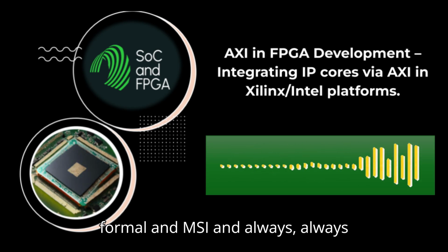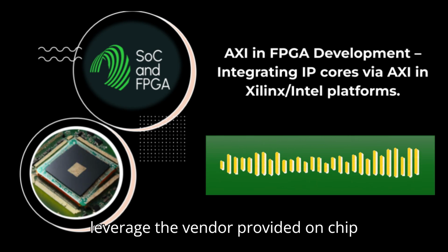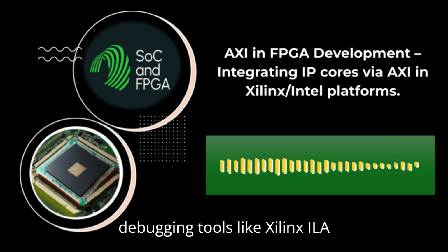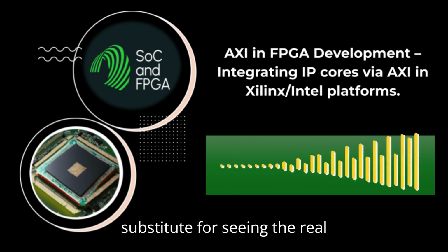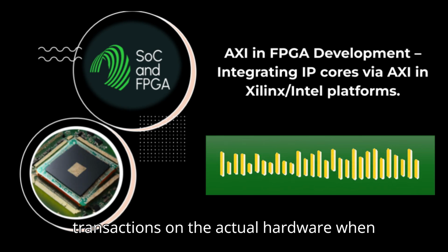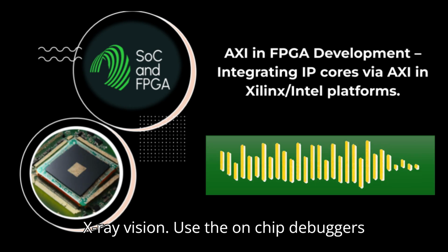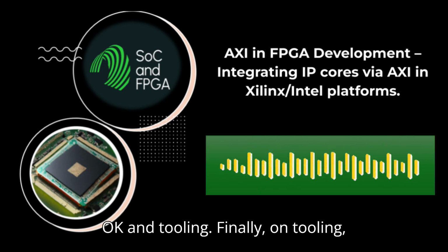And always, always leverage the vendor-provided on-chip debugging tools like Xilinx ILA or Intel SignalTap. There's no substitute for seeing the real transactions on the actual hardware when you're debugging tough issues. It's your X-ray vision. Use the on-chip debuggers and tooling.